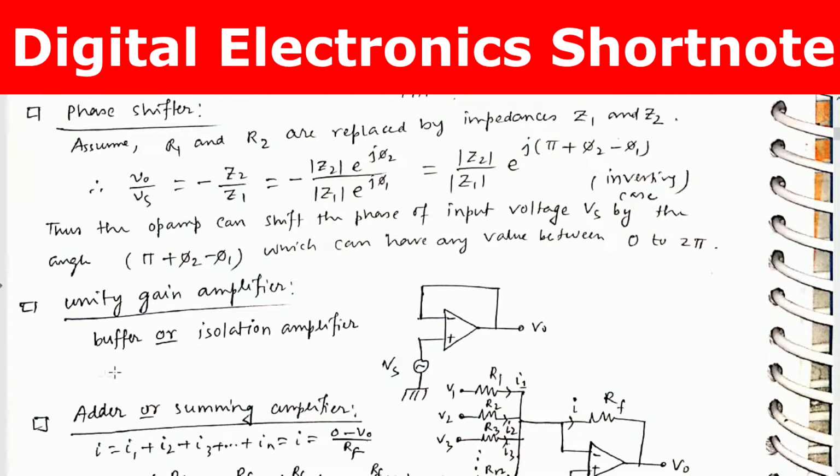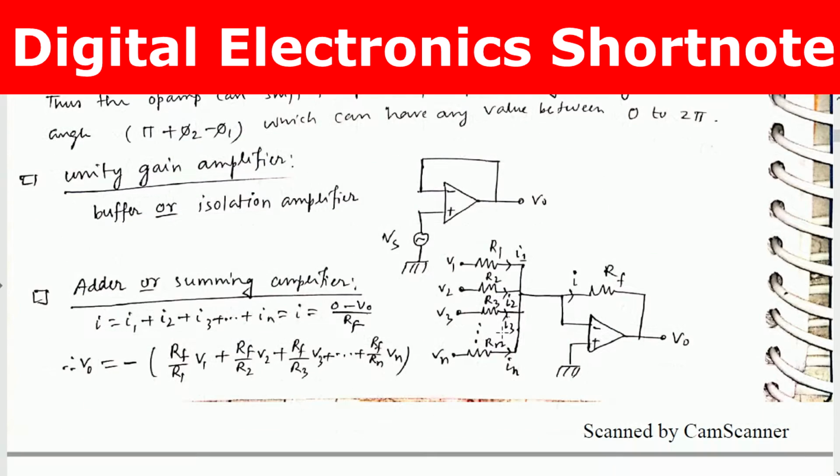Unity gain buffer or isolation amplifier. Look, the inverting input terminal and the output terminal, pins 2 and 6, are shorted, and it acts as a unity gain amplifier.